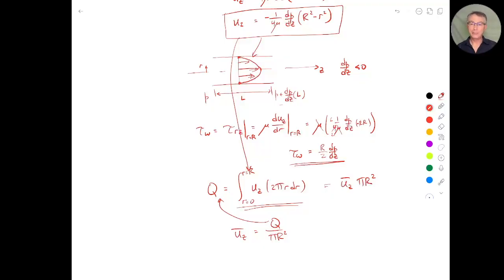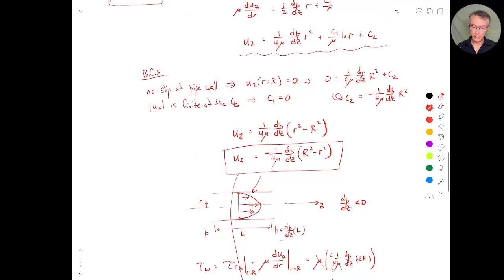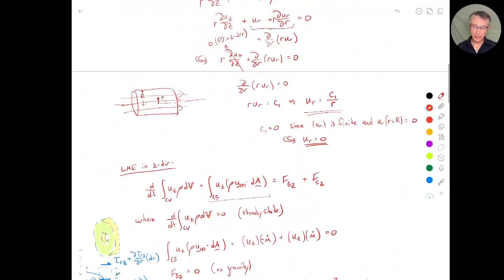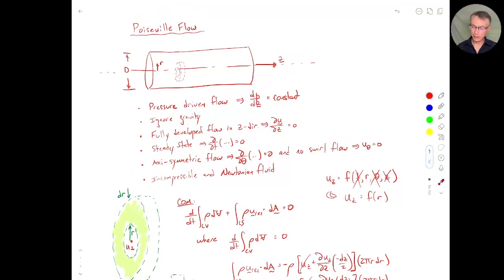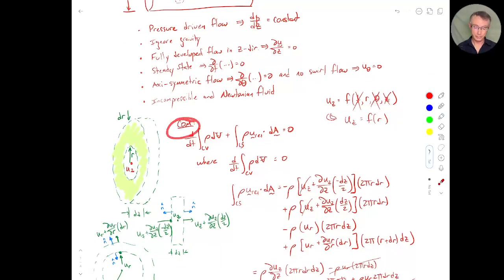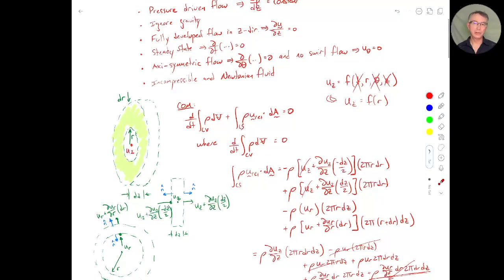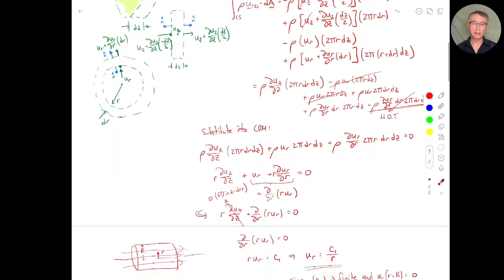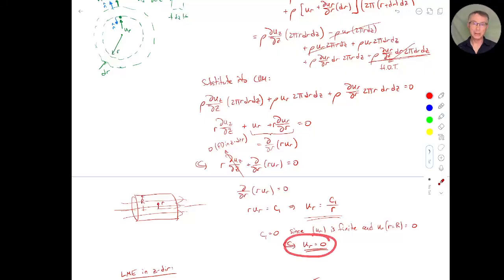So we're at the end of this video lecture. It's run a little bit long, but just to recap, what we wanted to do is find the velocity profile for a type of flow known as a Poiseuille flow. A Poiseuille flow is just a pressure-driven flow through a circular pipe. Okay, so we set up what our geometry is that we're interested in, and then we applied conservation of mass. That one just told us there was no radial component to the velocity. We sort of knew that going into it, but I just wanted to show you the derivation to get that.